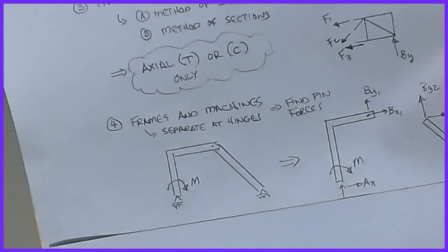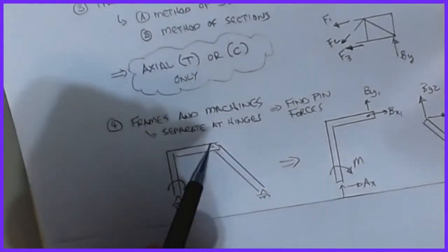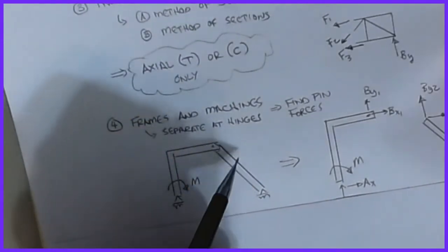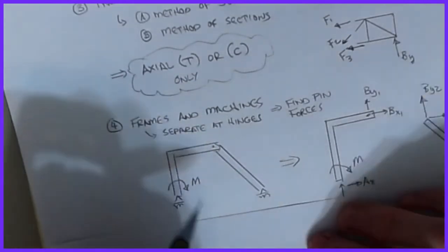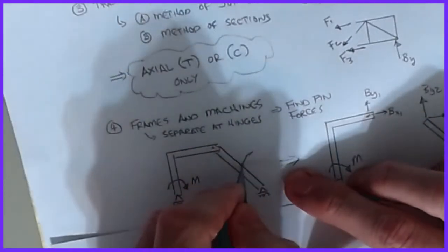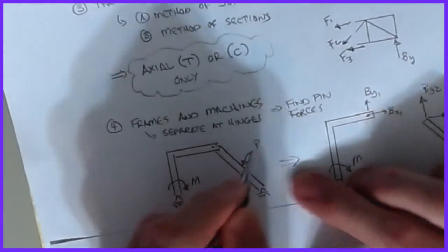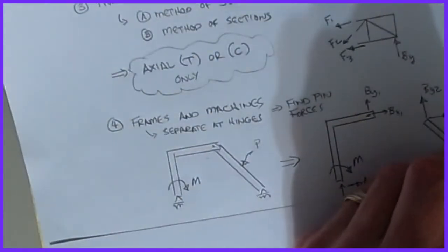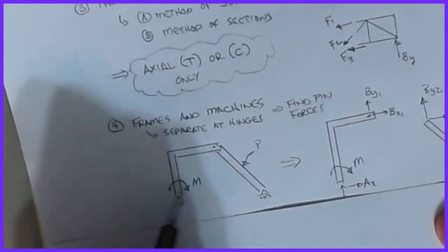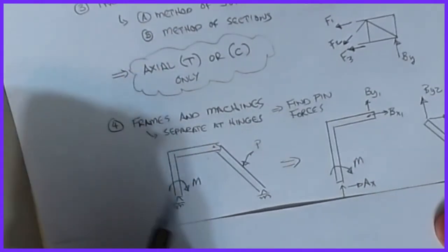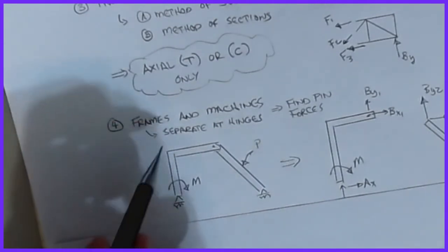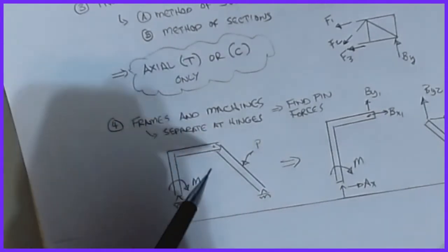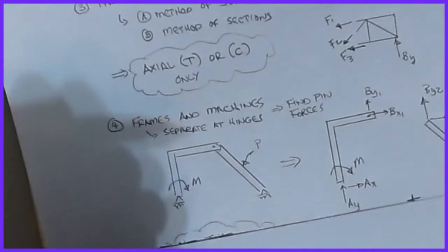So if I took just a simple system, well, this guy here may be a truss member. It's straight, pinned at the ends, and there are no loads, so that would be a truss member. I know this guy is axial, but say I didn't. Say this guy had some force P happening over on this guy here, and then I had a moment on this non-straight member. This is clearly not anything that we've seen in the upper parts of the list. So the methodology is you start looking for pin locations, and we look to separate things into pieces.